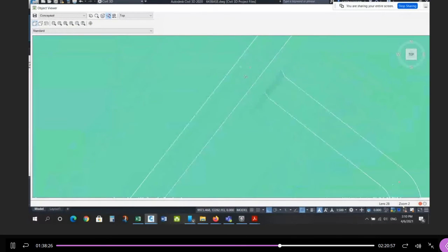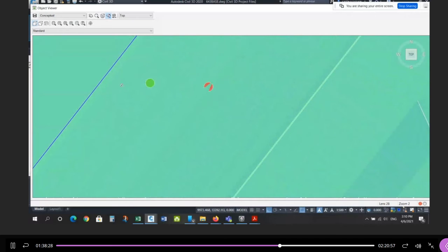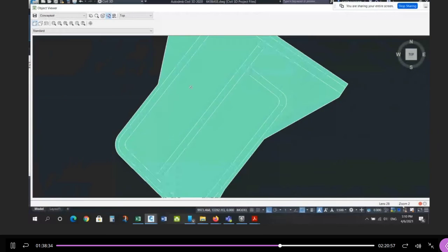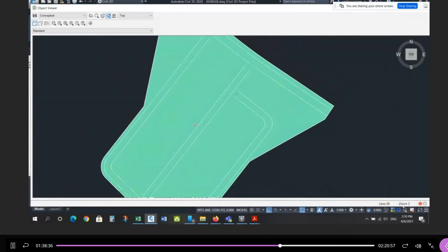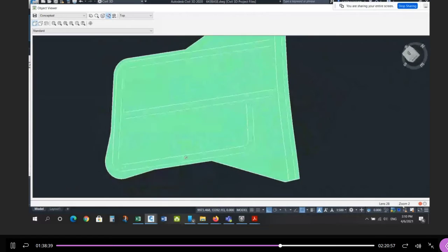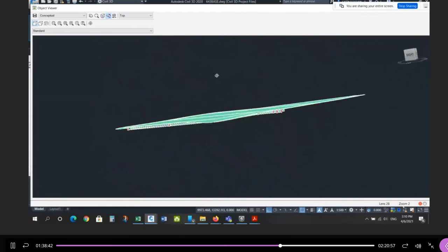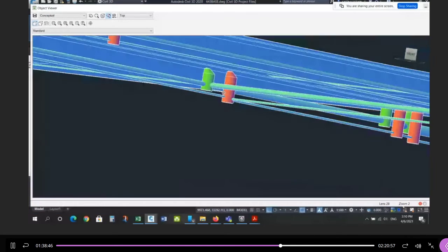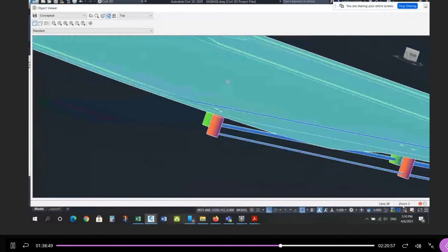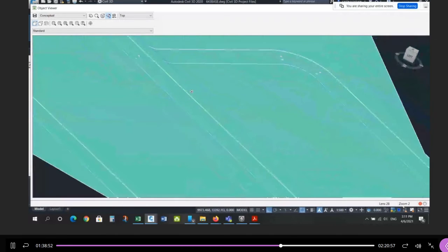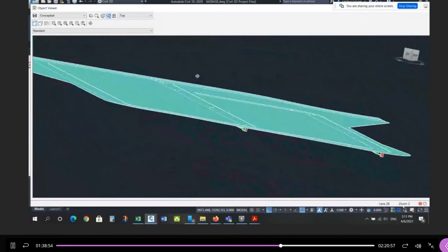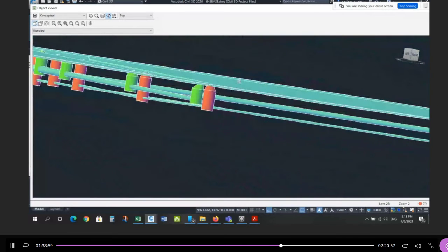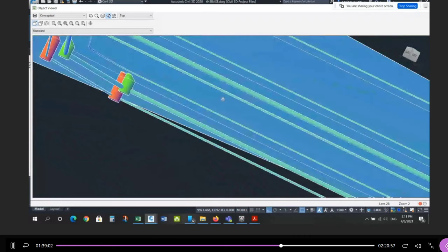Okay. So if you see here, if you look, you see the maintenance holes? Sanitary in the middle, storm off to the side. Everybody see that? When you're creating this information, after your design's done, what you're really creating is this. Ready? This network of 3D pipes. See that underground? And you can do a quick visual inspection to make sure where the crossings are, which is basically at the street A and B, that nothing is crossing, nothing is in conflict. Okay? So you can see how the road, how the maintenance holes, and how the pipes interact with each other.